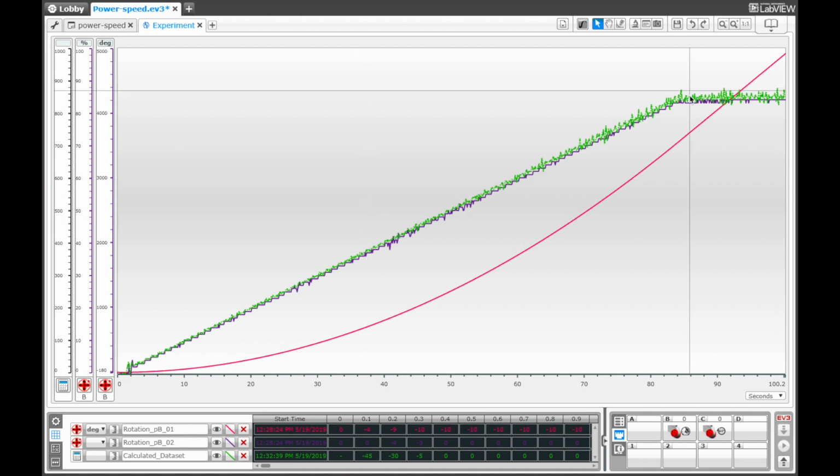1000 is the maximum number here, and you can see that the curves more or less overlap, which is interesting, and which also leads to the conclusion that LEGO here made the user interface a little confusing, because what we are seeing here in green is the derivative of the red curve, and the red curve is position. The derivative of position is speed.